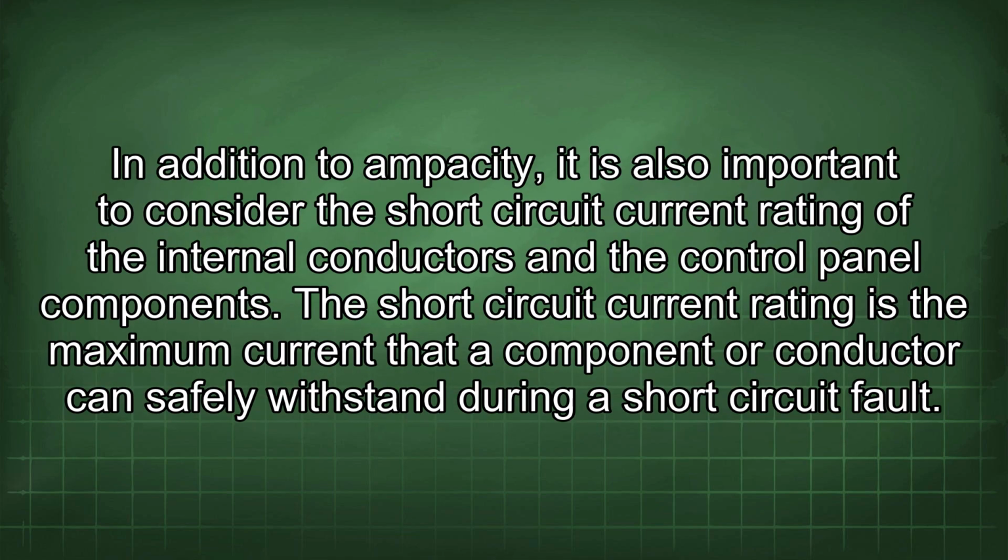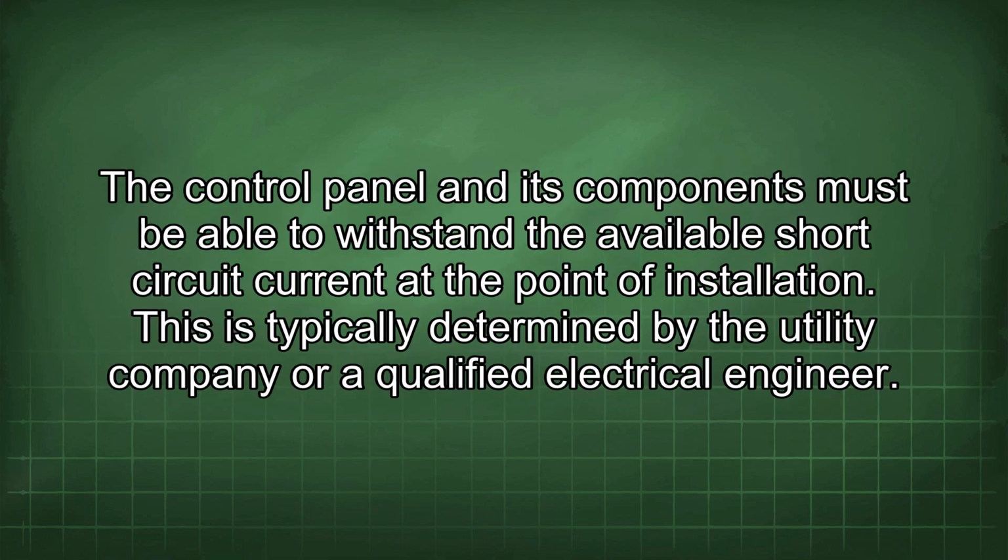In addition to ampacity, it is also important to consider the short circuit current rating of the internal conductors and the control panel components. The short circuit current rating is the maximum current that a component or conductor can safely withstand during a short circuit fault. The control panel and its components must be able to withstand the available short circuit current at the point of installation. This is typically determined by the utility company or a qualified electrical engineer.